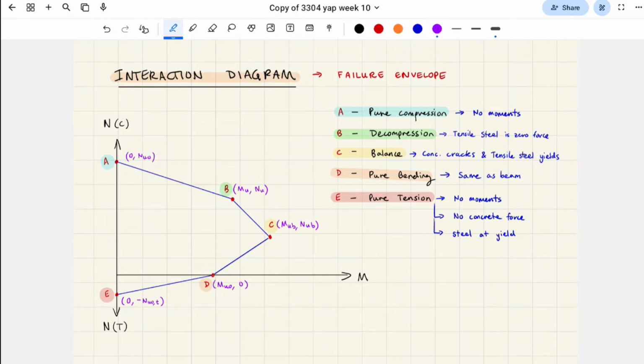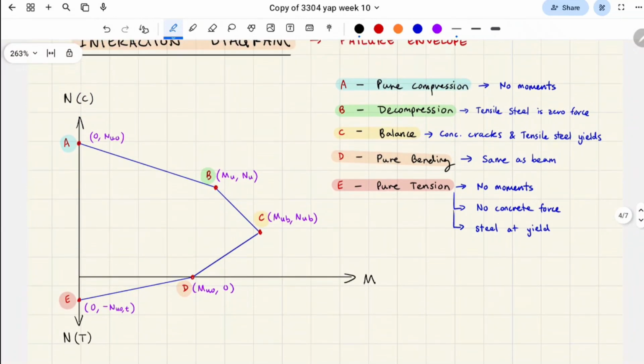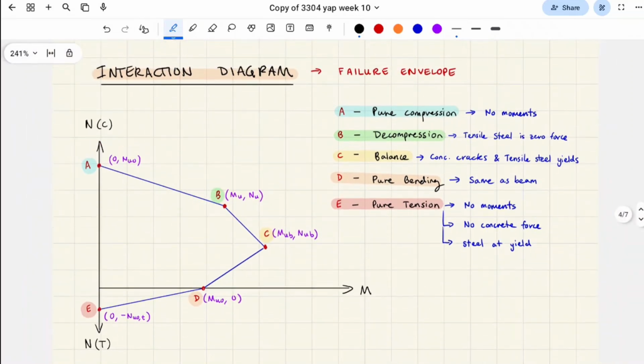I don't know. Does it have to do with the steel being squished? Does that make it stronger in some other direction? Kind of, but it's more about the concrete. You're thinking about the steel. Yeah. What properties do we know about concrete? I don't know. Well, we know concrete's bad in tension.